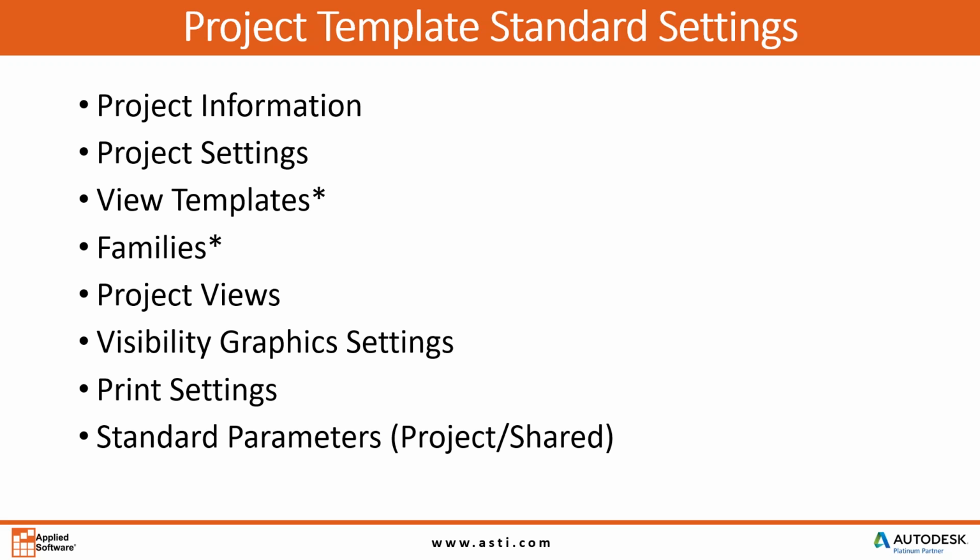So we'll talk about that in a second. Families should be loaded on an as-needed basis, right? And all custom families should be separate from the Revit library so that you can manage those separately in your templates if you need to.